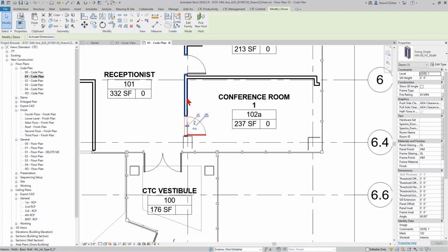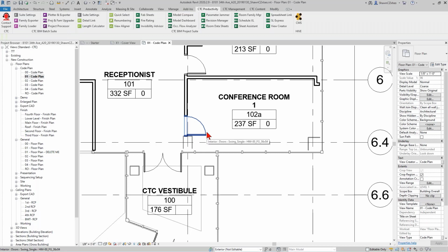In fact, I believe for this particular configuration, this door, if it has no glass in it, needs to be rated at 20 minutes. And if it has glass in the door, like a narrow vision or a full vision, then it needs to be rated at 45 minutes. The 3/4 of an hour is what the codes say that I was reading the other day about this. So that's all kinds of important stuff, right?